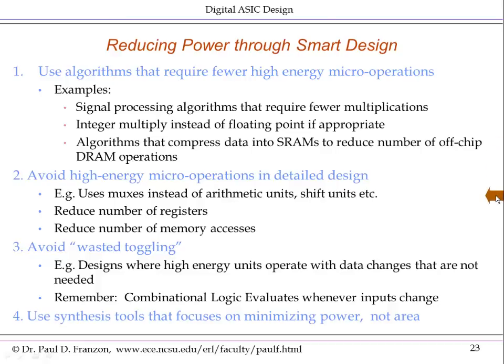That's early in the design. Later in the design, you want to be thinking about what are the micro operations that take high energy, and think about avoiding them. For example, use muxes instead of arithmetic units and shift units, etc. A big one is reduce the number of registers. Don't have unnecessary registers if your target is low power design. And of course, reducing the number of memory accesses, whether it's SRAM or DRAM, can make a big difference.